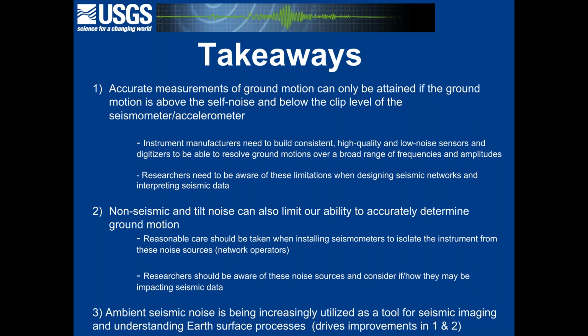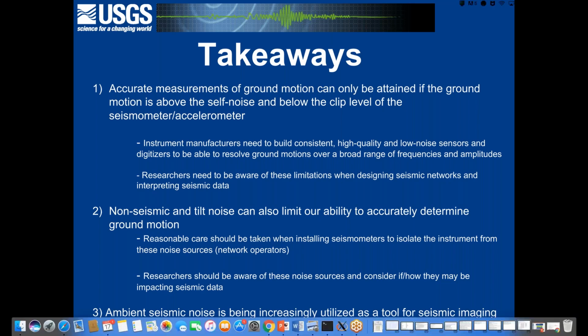Thanks, Rob. Next question's from Scott DeWolf, and Scott asked, did you say whether you evacuated the stainless steel pressure container? If not, why not? Yes, we usually do evacuate the stainless steel pressure container, and the reason for that is it reduces thermal noise. We want to get as many air molecules out of there as possible so that they're not knocking into the masses of the seismometer and causing noise. Also, when you evacuate the air, you pull out any moisture that might be in there. And of course, moisture can cause corrosion of components within the seismometer, which can create a whole other set of problems.